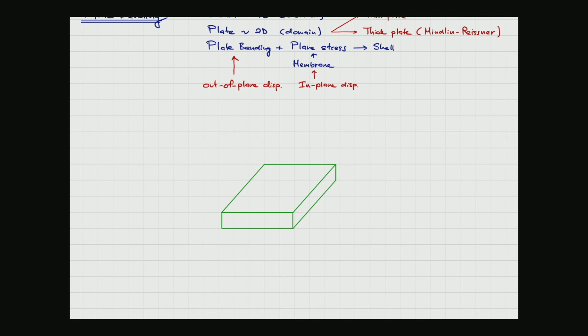So the conservative design approach using the bending element to determine the internal force required to provide the capacity of the cross section from flexure is going to give you quite a big safety margin.